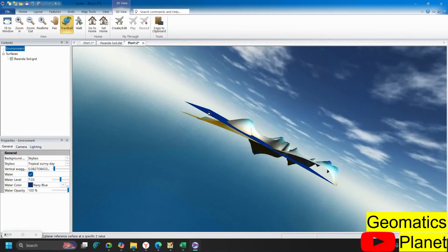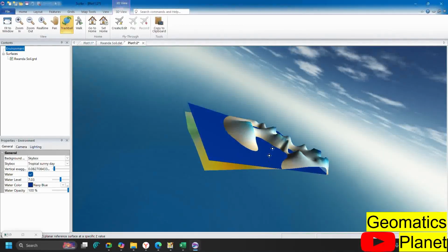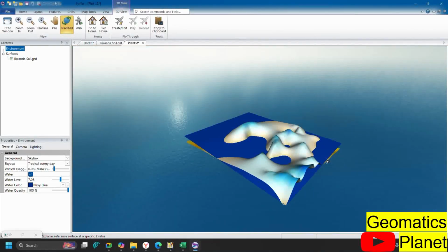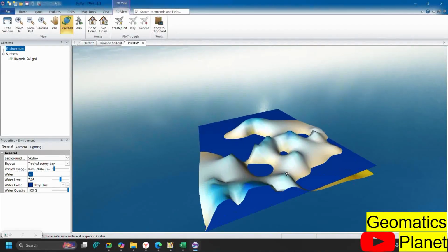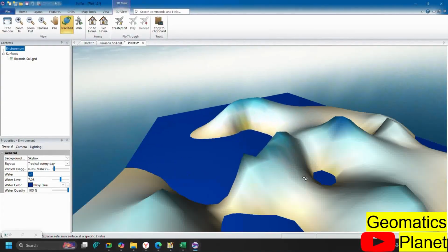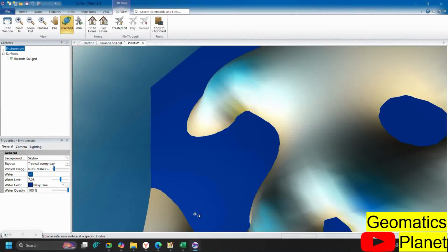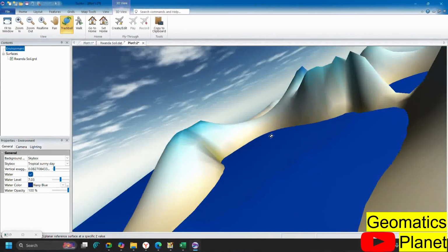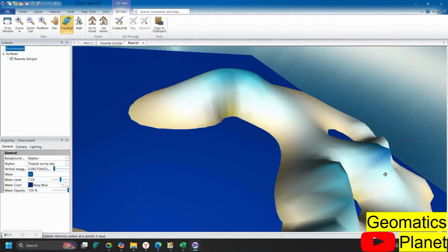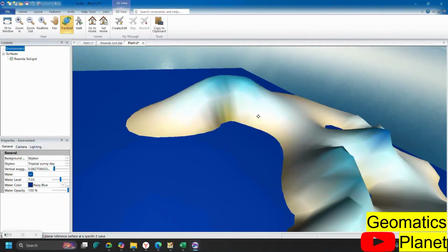Remember, like I said, you can use elevation. I am just using this because I'm talking about x, y, and z. So if it is an elevation, you can see now that you can use it to simulate. This is what flood would look like here. For example, you can bring building footprint here, you can bring any type of data here. If you overlay it on the building footprint, you can say, okay, because this water is going to reach here, that means these people that are staying here are going to be covered by flood.